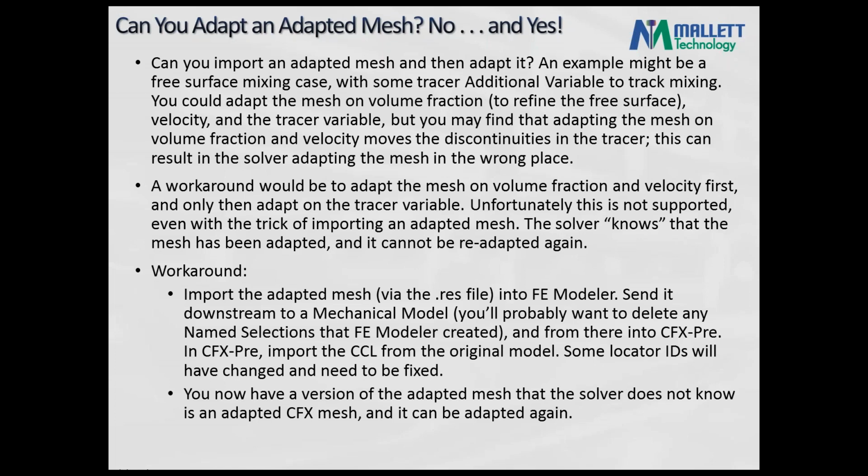Once you have adapted the mesh the first time, you can import that adapted mesh into Finite Element Modeler, send it downstream to a mechanical model, and then plug it into CFX. That, as far as CFX is concerned, is a completely fresh mesh. It has no knowledge that it has been previously adapted, and you can adapt on it.